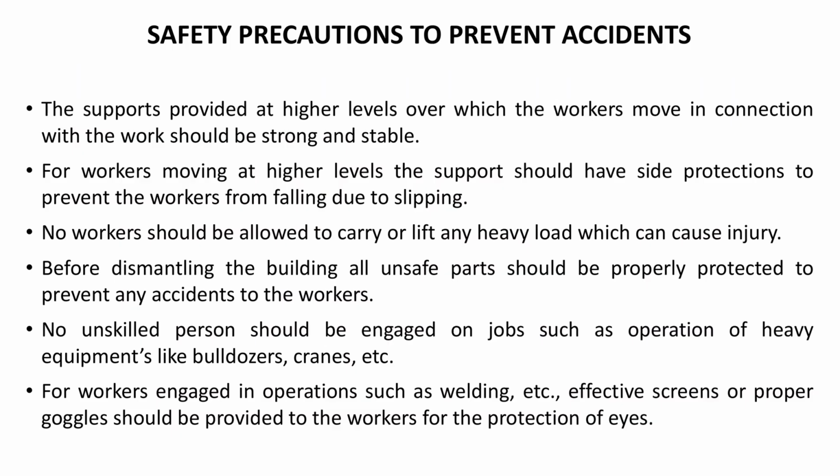Safety precautions to prevent accidents. The supports provided at higher levels over which the workers move in connection with the work should be strong and stable. For workers moving at higher levels, the support should have side protections to prevent the workers from falling due to slipping.